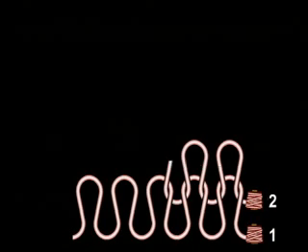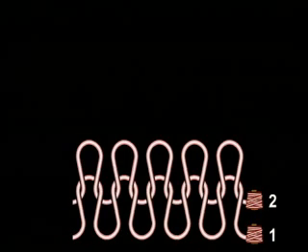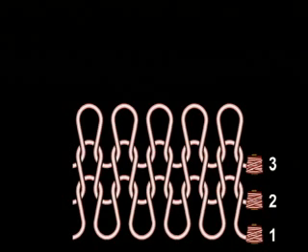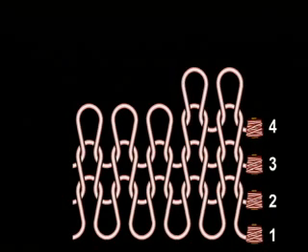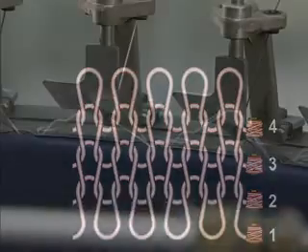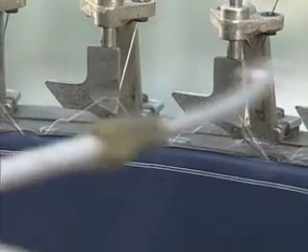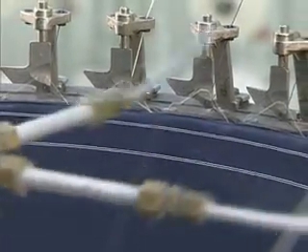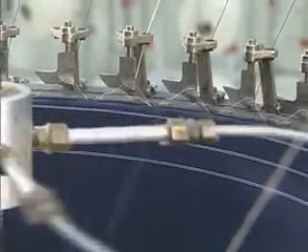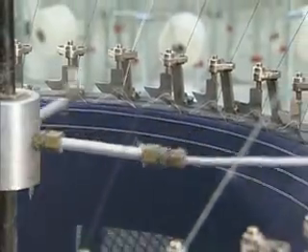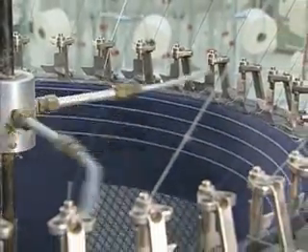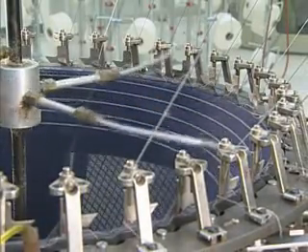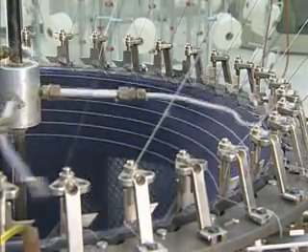Weft knitting is accomplished by loops formed in a horizontal manner by adjacent needles. It uses one continuous yarn to form courses or rows of loops across a fabric. The most common machine used for weft knitting is the circular knitting machine. This machine creates a tube of fabric in a spiral configuration around a cylinder. The number of needles on the machine, the stitch length, and the yarn size determine the width of the fabric. One revolution of the machine completes one course for each yarn fed.